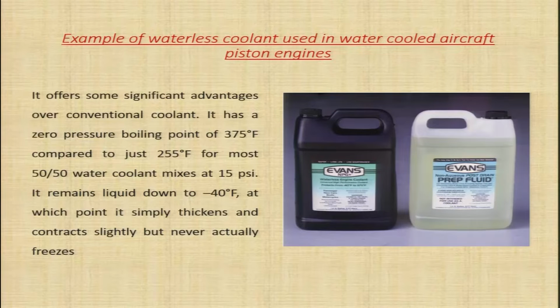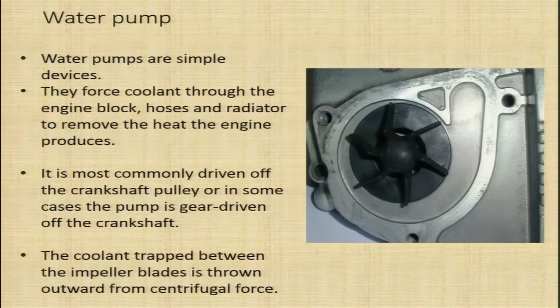These types of coolants are being widely used in the engine. Here you do not have to mix them with water, and we just have to use them directly. They have much lower freezing points and better operating characteristics. In the liquid cooling, we mentioned a water pump. This water pump was directing the coolant from the radiator to the engine cylinder head.